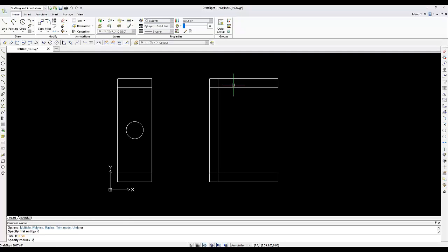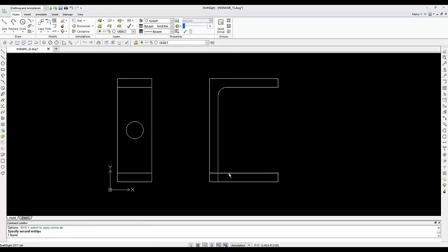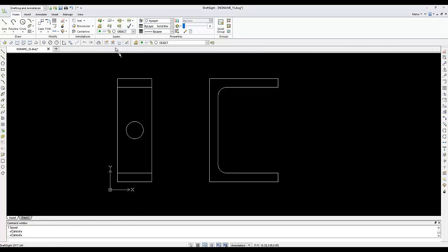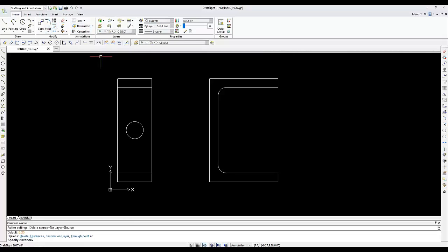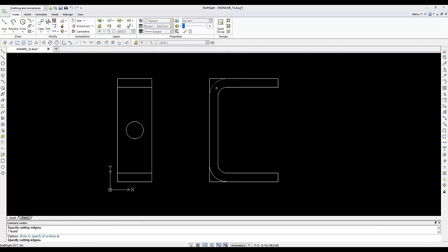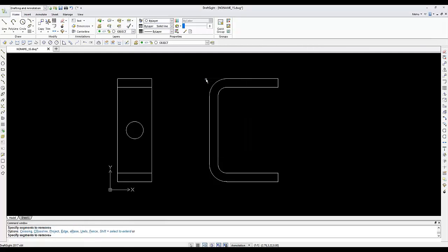Let's specify that radius to say 25, which will represent a 1/4 inch. Place it here as well as here as well. Let's do another offset for that thickness. And finally, let's trim away this sharp corner here so that it can look like a bracket.